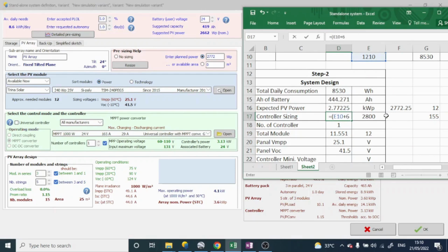So we have 6 batteries, so we write 6 multiplied by the charging current for each battery, which is 15.5, as we are using a C10 battery having 155 ampere hour. So we write 15.5 as the charging current multiplied by the voltage of an individual battery. It means the current and the voltage give the wattage capacity of a battery, and the total number of batteries is 6.